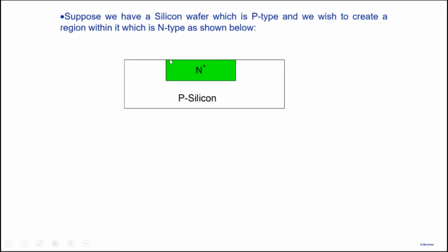So you can already see that if I take a piece of silicon and create an n plus region like this, I'm basically creating a PN junction here. I'm creating a diode at this particular point. And if I make a metal contact here and a contact here, I will get a PN junction, a diode here. Now, the point is that I want an n plus region only here. For example, you may want 2 diodes. So you may create an n plus here, and an n plus here also. So you'll get one diode here and another diode here. Okay. So you want to create an n plus region selectively in a certain part of silicon.